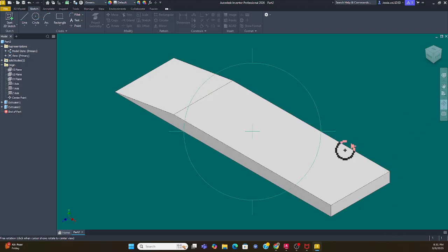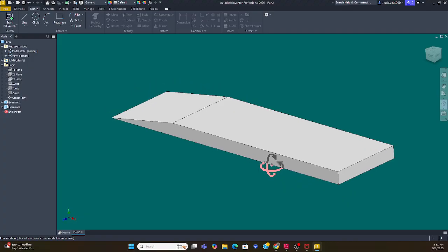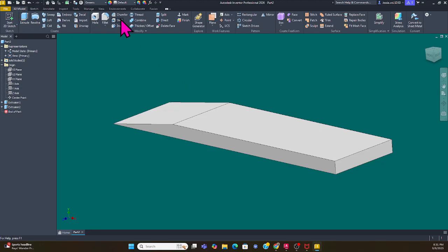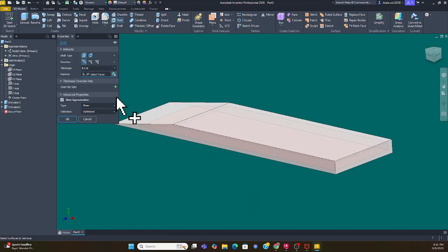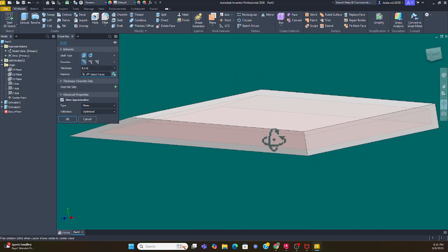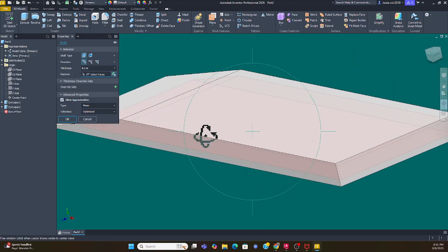Now if I rotate this, you can see that everything is solid, but the body of the air skimmer at the bottom is hollow, including the front. So we're going to use a 3D model here. We're going to have to shell it. We're going to go to shell and set the thickness of paper. Right now, if we zoom in a little bit, you can see the thickness is really big there, a different color as you see. The thickness is too much. So I'm going to hit escape, and then I'll change this to 0.01.